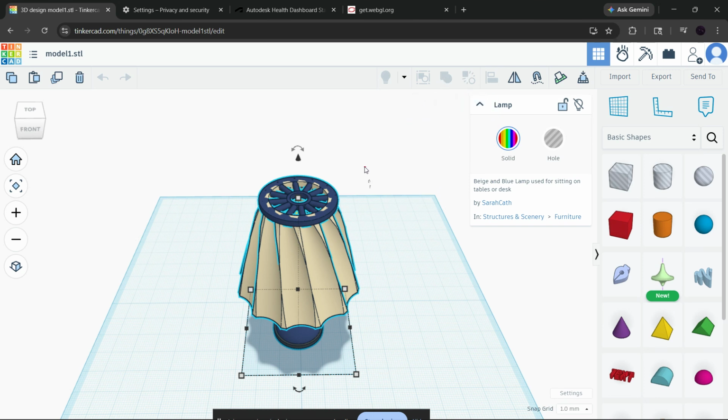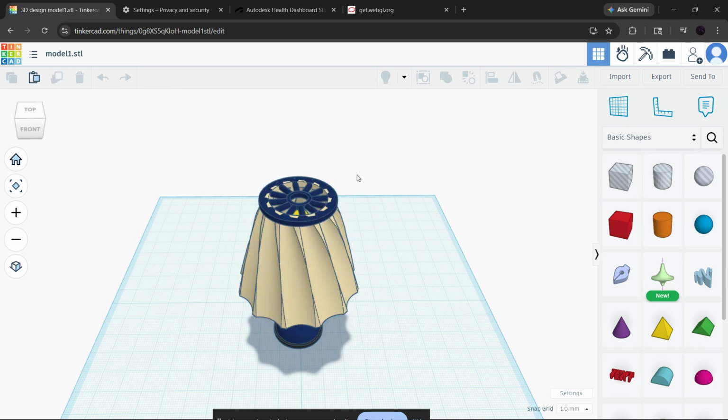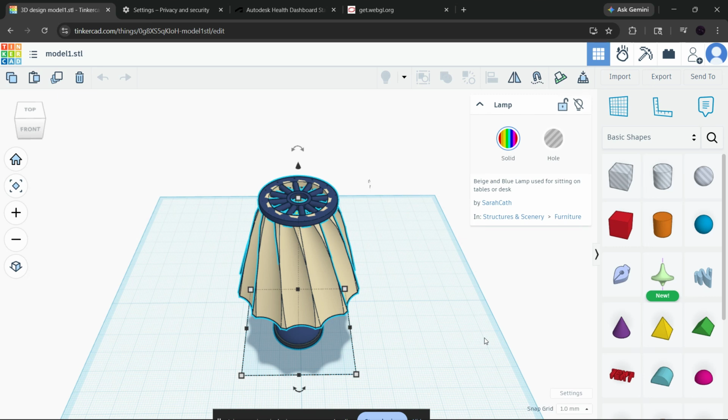If you imported a complex SVG or a high-resolution STL file, that may be the real cause of the problem. In that case, simplify the file before importing it again. Reducing the number of nodes or mesh details can make a huge difference in performance.